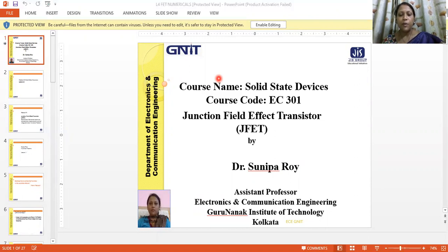Here the JFET operates as a constant current device because ID is relatively independent of VDS. It is due to the fact that as VDS increases, channel resistance also increases proportionally, thereby keeping ID practically constant